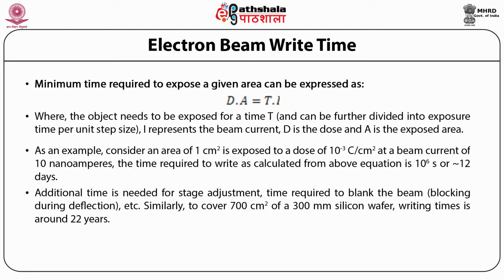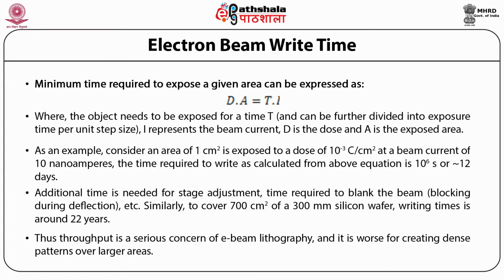Similarly, to cover 700 centimeter square of a 300 mm silicon wafer, the writing time is around 22 years. Thus, throughput is a serious concern of E-beam lithography, and it is worse for creating dense patterns over larger areas. This seriously precludes any commercial scale production using this technique.